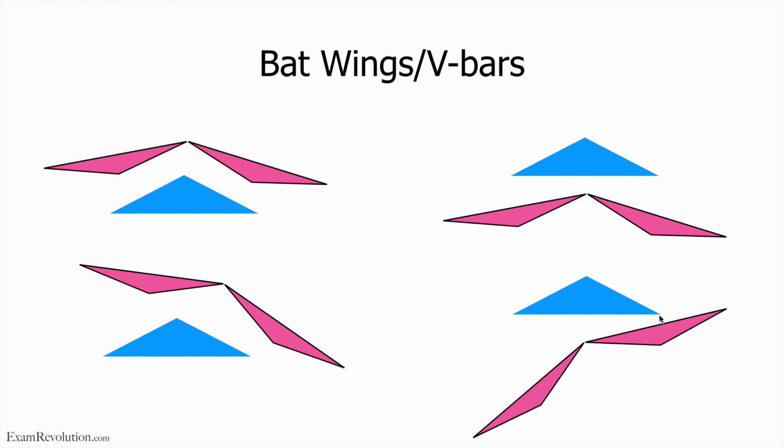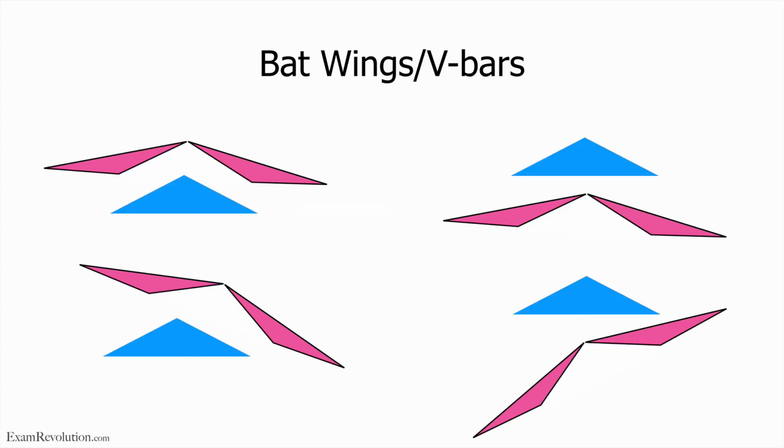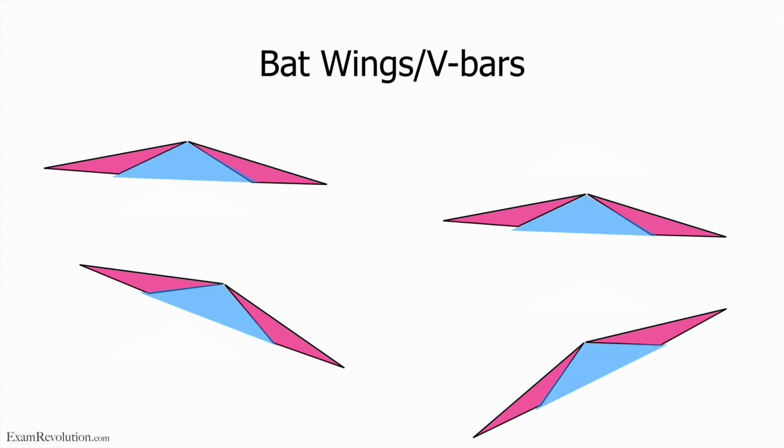And in this case, there's the aircraft's nose. Now the bars, the bat wings, are showing that you must go down and to the left. So once again, imagine yourself putting the triangle in the bars over here. So this is what it's going to look like. You can see in the first picture we've pitched up and we haven't banked. The second picture, we have pitched down and we haven't banked. So just from that position down into the bars.